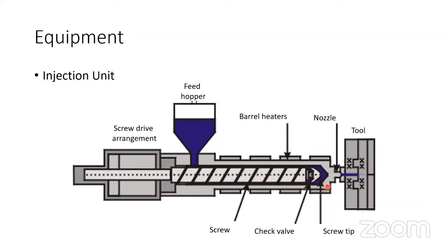And the front one, the nozzle temperature, is somewhat less, maybe 4 or 5 degrees less as compared to the metering section. Therefore: lowest temperature, middle temperature, highest temperature, and then 3, 4 or 5 degrees less than the metering section at the nozzle.